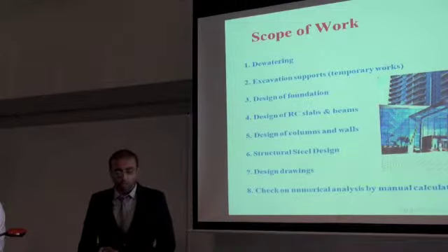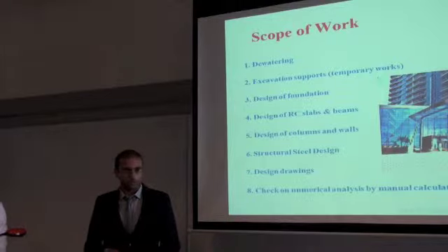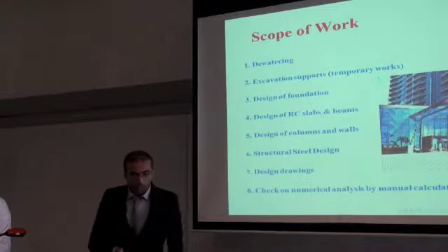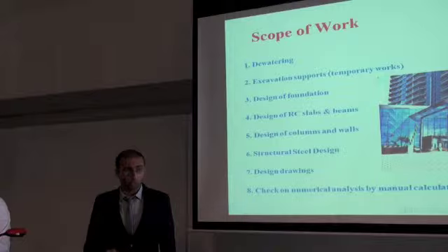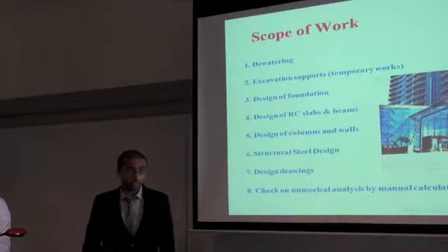Moving on to the design of foundation, we'll have to calculate vertical loads due to gravity and lateral loads due to wind and seismic forces. We'll also consider the lateral pressure of soil and lateral pressure and uplift of groundwater. Then moving on to the design of columns and walls, where the seismic forces and wind forces are really significant, we're going to explore the modes of vibration, and we're going to perform dynamic analysis for our structure.